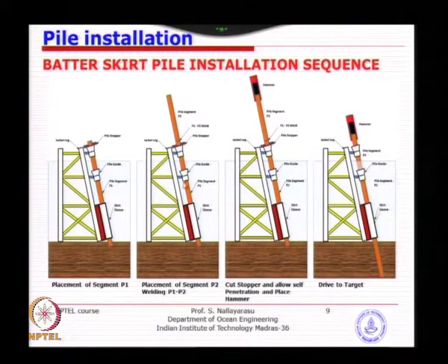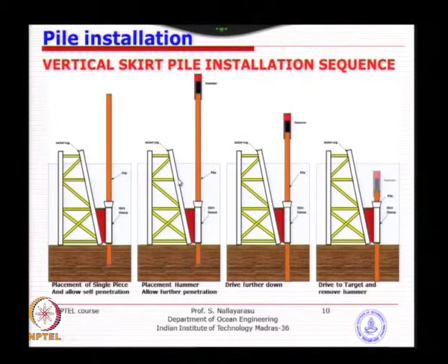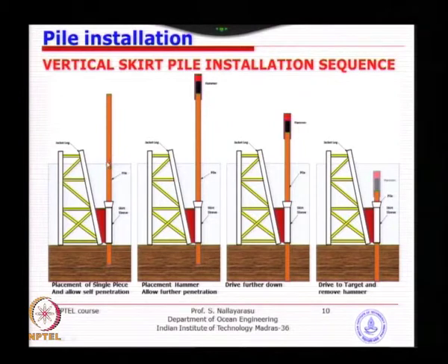Many times people prefer this, because it is under our control, and supports can be provided. You could ask why we can't provide support here. That is what I showed in the first picture: the distance between the jacket and this could be 10 to 15 meters, as you may remember from the other course where we looked at the jacket batter. So providing support somewhere here will add construction time, and normally we do not recommend it, because that will be more offshore work.